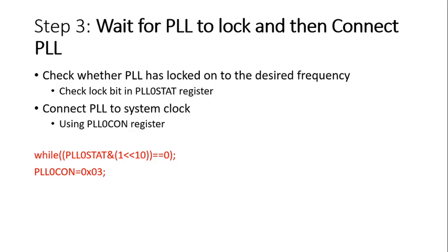I have told you that first you have to enable it and then you have to connect it. So first you have to set the PLL0 control register, the PLL0CON register, to 0, 1. Sorry, I think that was remaining there, I will put it here.